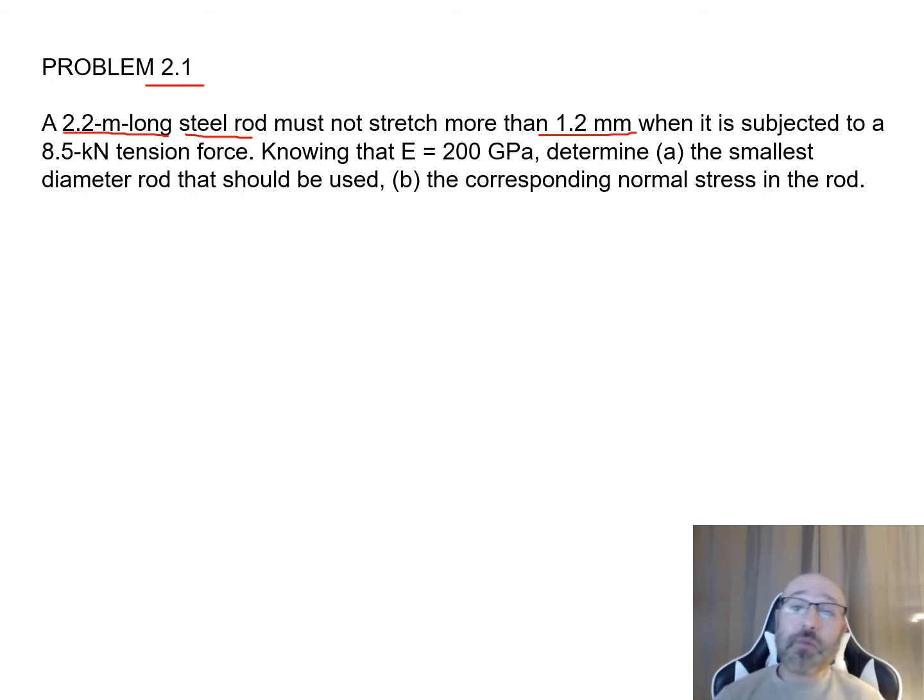Right off the bat, as I'm reading through this problem, there's a couple things I really want to pay attention to. First thing here is units. They're giving me the length in meters, but they're giving me my elongation here in millimeters. So I really want to pay attention to that and make sure when I start creating my setup page that I determine what units I want to use for this problem and do any of the conversions that I may need to do to keep everything in the right units.